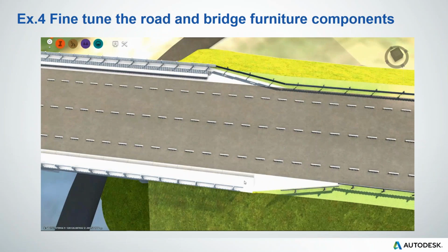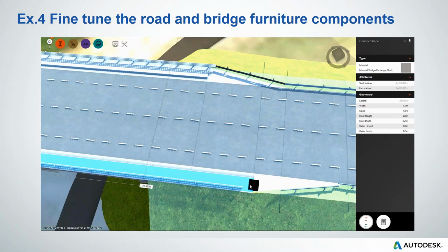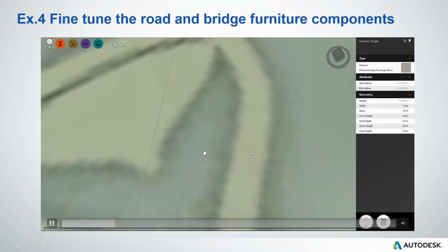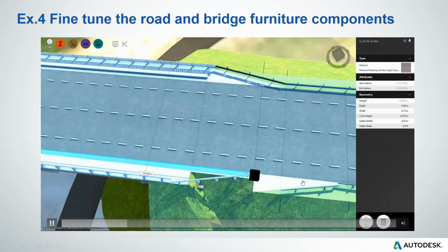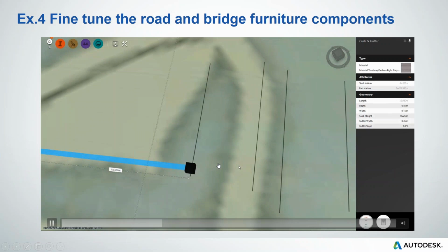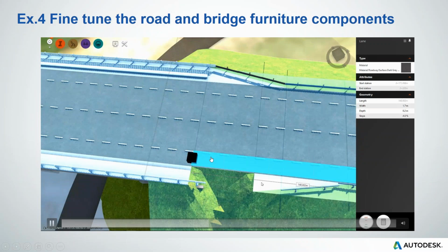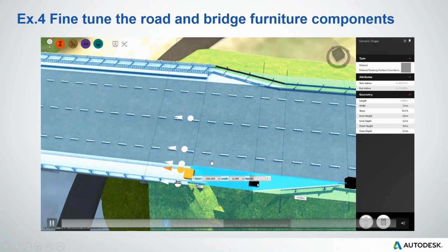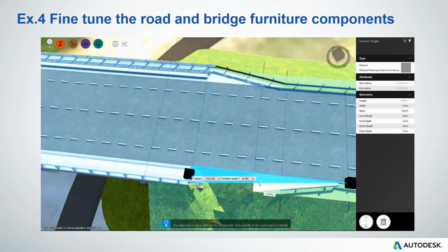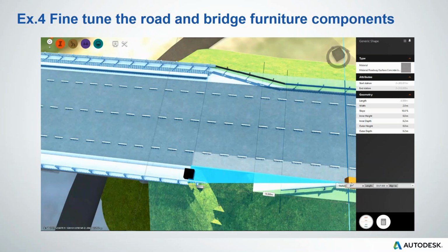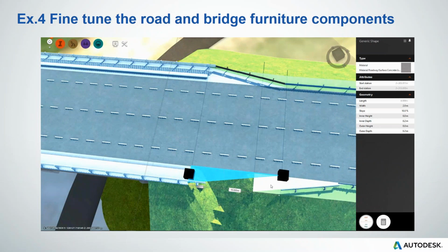The fourth example will be to edit or modify the road components for roads approaching the bridge, or basically coming in and out of the bridge. So here we're changing, for example, the sidewalk, we're changing the guardrail, we're changing maybe the lane width, etc. All of that is possible inside of Infraworks, and this is basically some very basic functionality inside of Infraworks for road design.